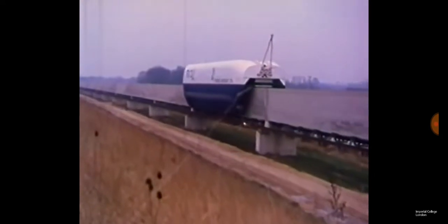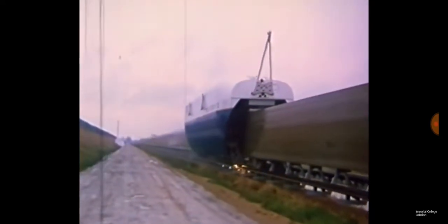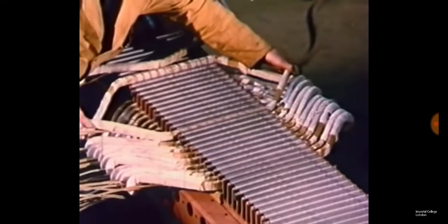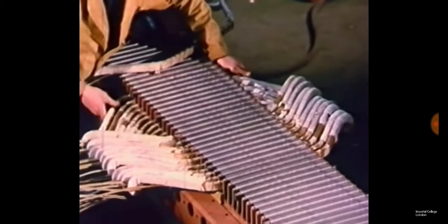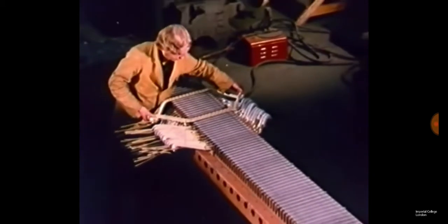This is no model. This is the real thing. An air cushion vehicle running on a concrete track in Cambridgeshire. This vehicle is driven by a linear motor which is designed for speeds up to 150 miles an hour. Nearly 2 miles of track, so flat and straight that the eye can detect no flaws, is an impressive sight in itself. And this is the motor that drives it in course of construction. Coils are being dropped into slots in a laminated steel core, and the whole motor is about 12 feet long.